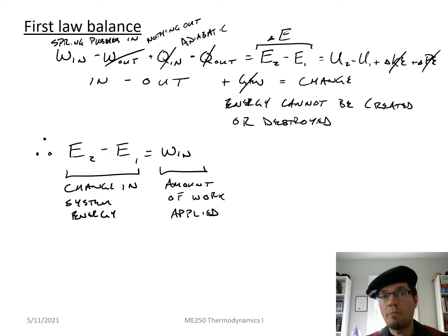And a really common question in thermodynamics is, what is the work or what is the heat transfer necessary to go from that state 1 to that state 2? That is thermodynamics in a nutshell, and that is what we're going to be doing again and again in this course. We're always going to be asking, what are the states that we're in, and writing out in minus out equals change. Work in, heat in, mass in, work out, heat out, mass out equals change in energy of the system. There is no generation of energy, so we're always going to drop that term.